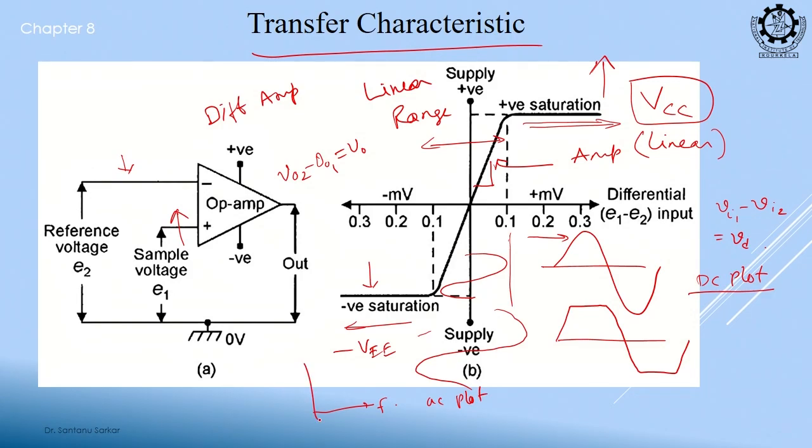Understood? How many variations? If the x axis is time, it is a transient analysis. If the x axis is a DC input, it is a DC analysis. If the x axis is frequency, this is an AC analysis. Where do we see that frequency AC analysis? In which kind of chapter have we seen it? We have seen it in filters and oscillators, because frequency was important,